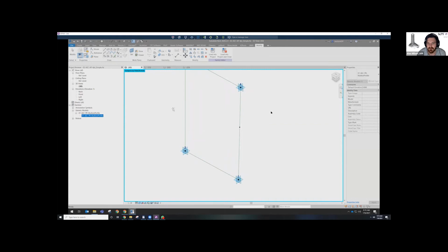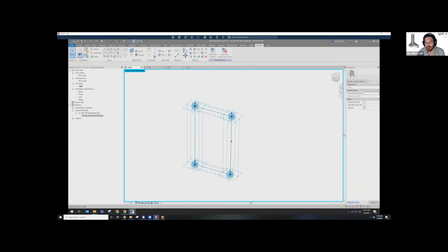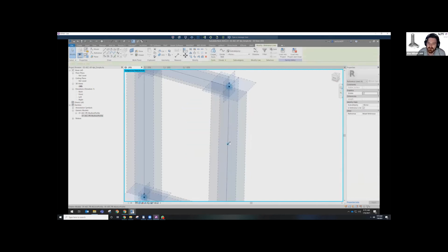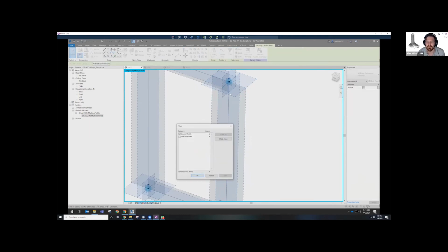Then place the family, so drag it out onto the modeling environment, place on work plane. Then you can see it's automatically snapping to that point. Now at this point you have your profile locked to that point. We then select the chain of reference lines. You can select one. Generally, it'll select the entire chain, but obviously tab is a good shortcut if you need to jump between a single and the entire chain of the sweep. Then we also just select the profile. So at this point, you can see in my selection, I have the lines and the profile.